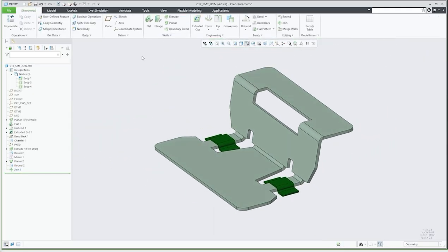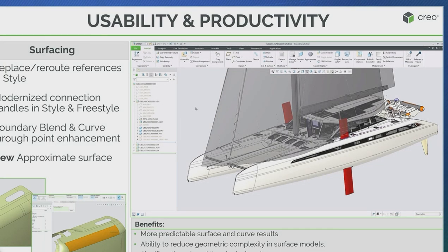available on all parts. In Creo 11, we introduced new spot welding capabilities and workflows with the introduction of joint members. In Creo 12, we have continued to enhance this, providing richer information and control over stacking information and sequencing control. We've also improved the overall visibility of spot welds, making it easier to manage products with large numbers of spot welds. We also expanded our weld export information, now supporting groove welds as well as fillet welds, enabling streamlined processes for the creation of offline programming of welding robots.